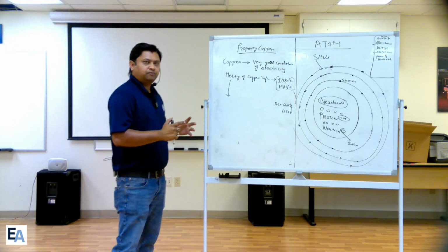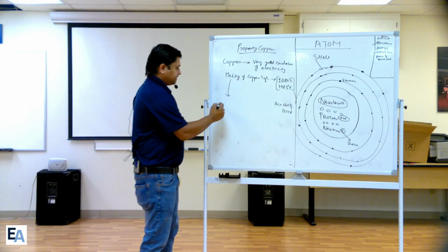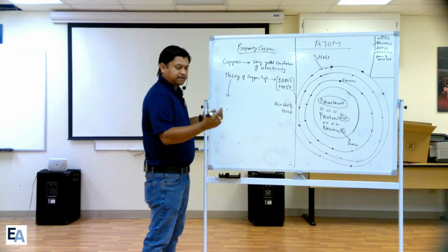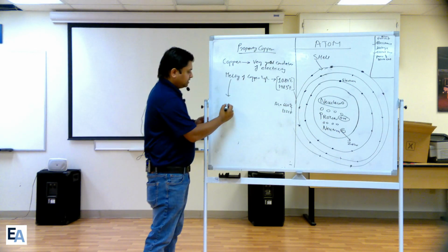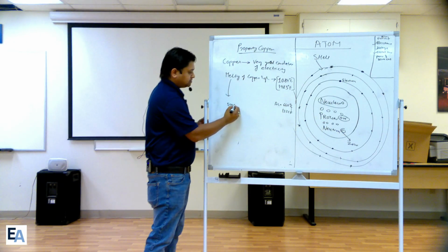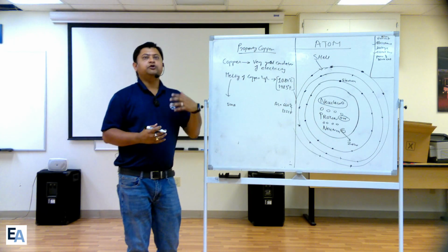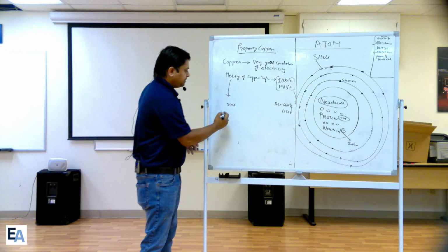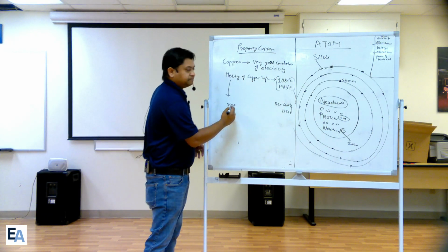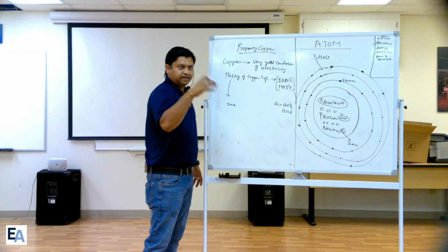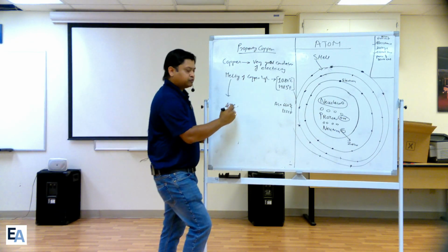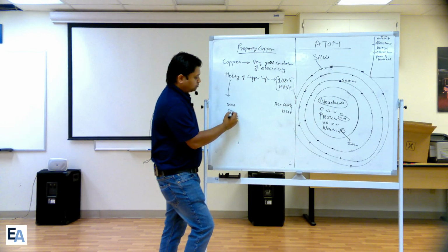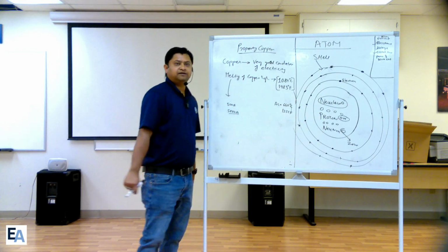So if your transformer is designed to withstand, for example, say 500 amperes, during the short circuit it may see, I'm not going to go really deep into the design, but just for your knowledge, about 5000 amps of current.